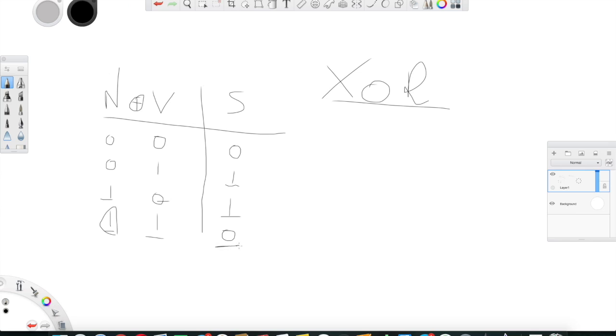Therefore, the sign bit is 0. Here, the actual sign was 1. However, I had an overflow, meaning that the sign should have been a 0. The overflow means that the sign is wrong, whether it is 1 or 0. Having 1 in the overflow, I repeat, does not mean that it should have been a negative number. No. Here, the number is a negative number, but having 1 in the overflow means that it should have been a positive number.